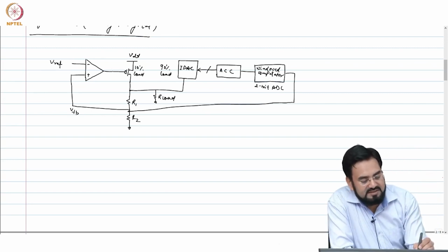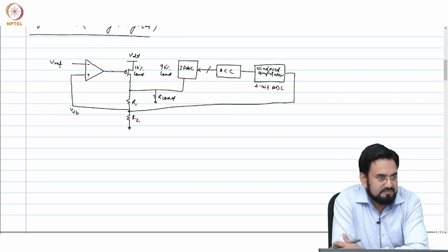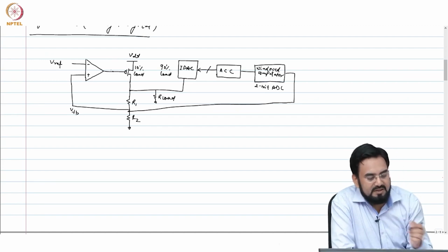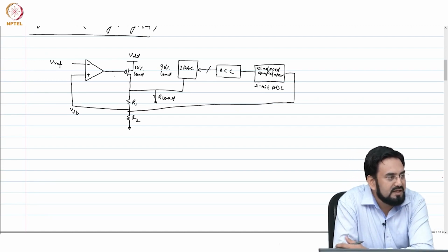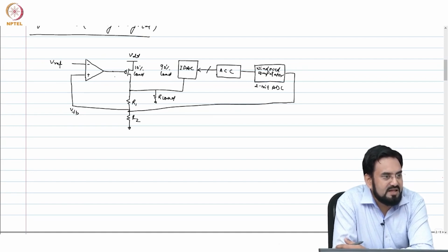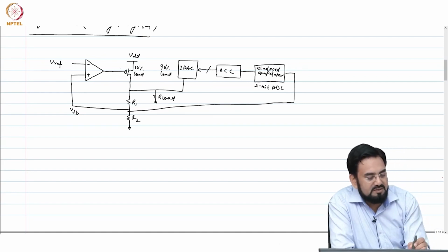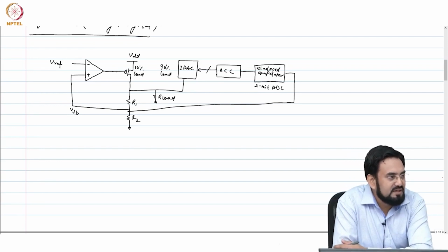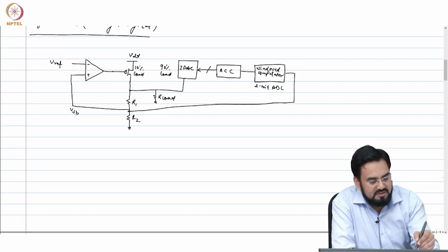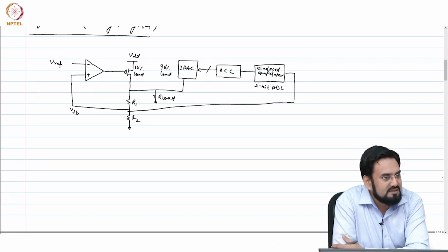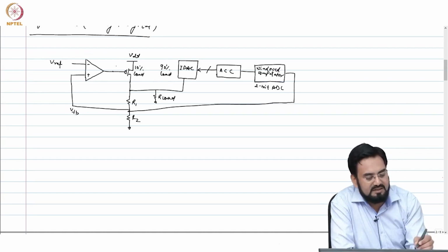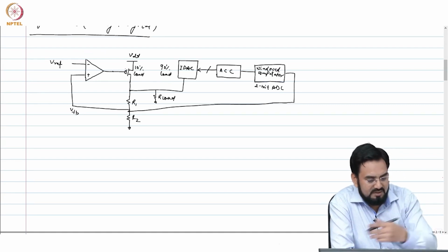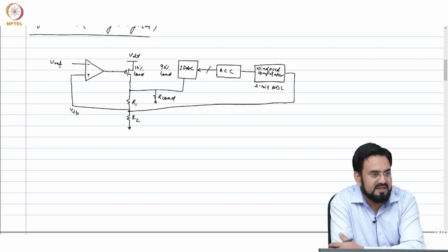Other way, you can sense this gate voltage also. So let's say you have sized this for 100 millivolt overdrive voltage. Okay, so which means at 1 milliamp your VGS minus VTH will be 100 millivolt. Okay, and you know VTH roughly what is that? So let's say 500 millivolt, which means your gate voltage will be 600, plus whatever, because it's a difference from VDD.